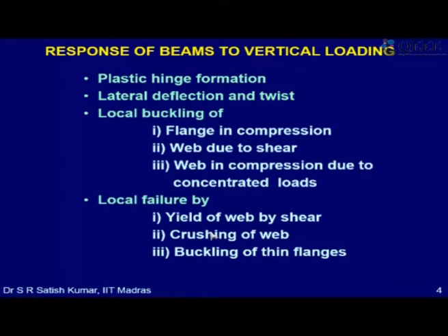But in reality, the flow of load or stress is pretty complex. So if I take a simply supported beam and apply a point load, this flow will be going like a parabolic arch. There will be a compressive stress trajectory by which the load will go into the supports. There is also a tensile stress trajectory, which is like a cable. So the beam acts as if it's an arch plus a cable stuck together, and that's how it actually transfers the load. Okay, and as a consequence, there are other forces which are coming in. At the support, the web is getting compressed, there is a stress concentration. So there are a variety of failure modes in beams.